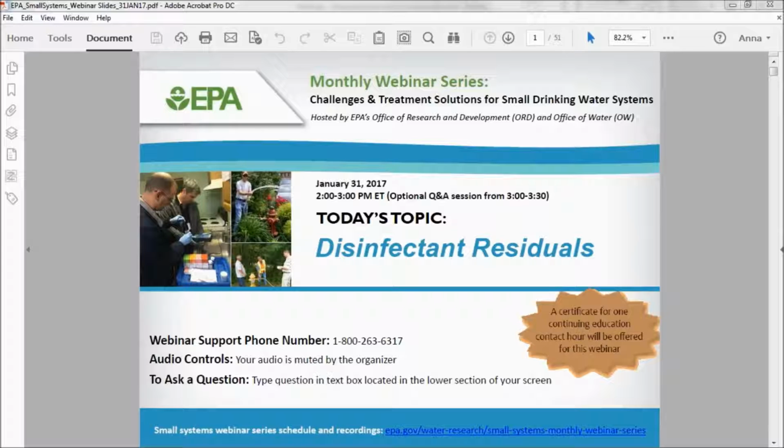Okay, great. How do you regulate the flow of your hydrant sampler? How accurate do you think it is? We use a commercially produced flow regulating valve. The one we use for the hydrant sampler limits it to 20 gallons per minute. The manufacturer gave us some curves depending on pressure. It'll tell you what your corresponding flow rate is, but we haven't ourselves measured to determine how accurate that is. But we have pretty good confidence in it.